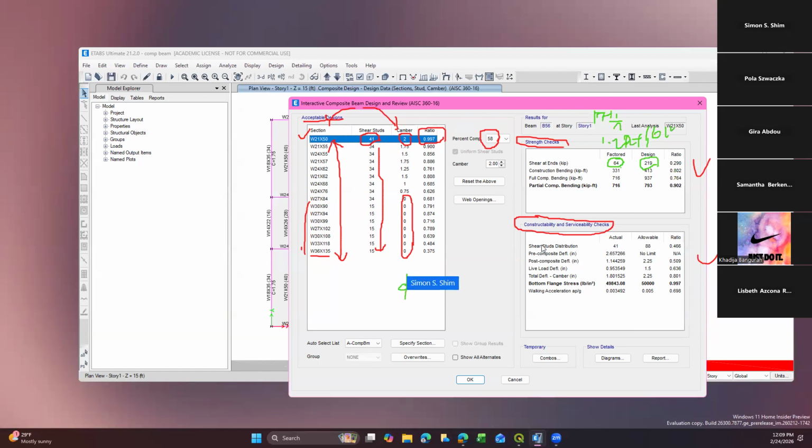Typically, the shear nominal capacity, phi Vn, is roughly 0.9 times 0.6 times Fy times Aw, the area of your web member. That's the shear capacity. So, okay, shear is no issue.